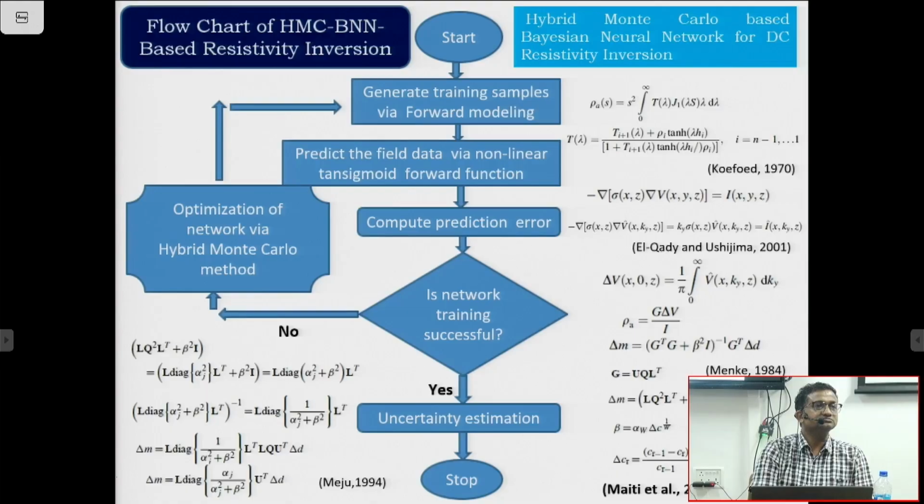Excuse me, sir. How can the true resistivity from the inversion be a true resistivity while there is an assumption that there is no variation of resistivity laterally? Resistivity can vary in the whole body, because we can vary it non-linearly and laterally.